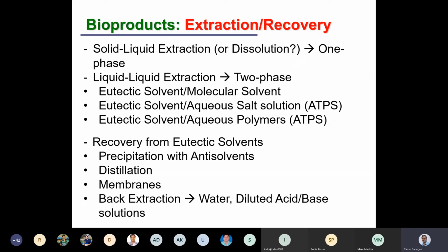You have to test the solvents with the resins to know if the resin is going to be dissolved or have an interaction that modifies its properties.